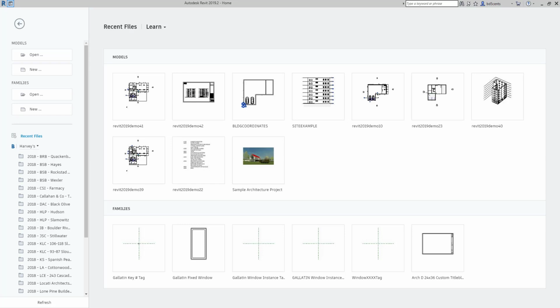We've discussed a little bit about purging in class, but I'm going to go over a little bit of that as well, just from what we've done throughout this course. And then a little bit of transferring project standards and understanding what that allows you to do, as well as discussing some of the variables of how you can use it to steal from some of your other Revit projects and what benefits you get from there.